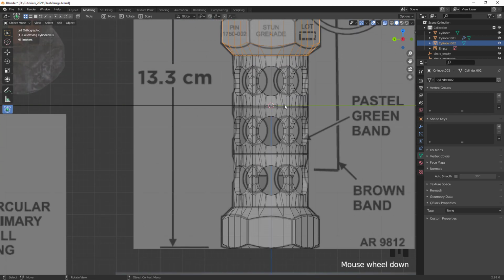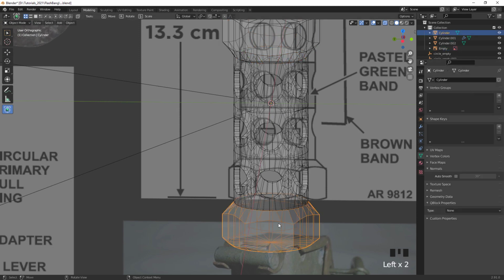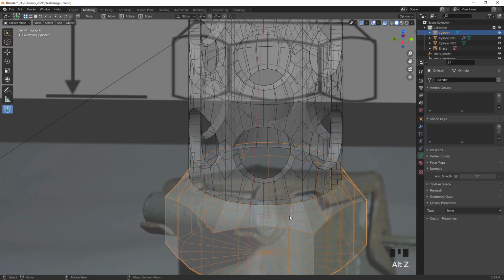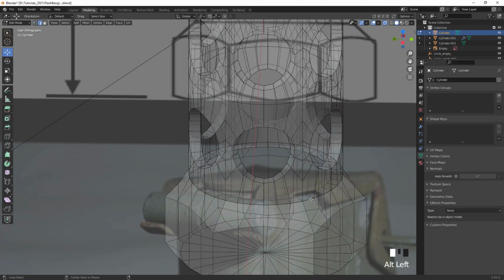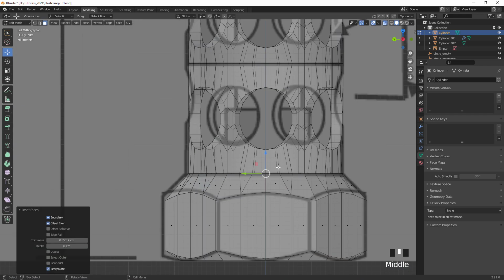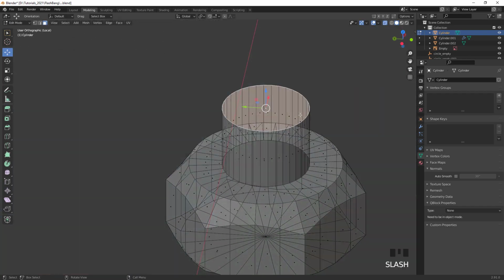So now we have made use of the same element from the bottom at the top, and we didn't have to do the work twice. So we are gonna treat these objects differently though. I'm gonna take this element here and say F on it while we have an edge loop for it. And then I'm gonna use the inset to essentially have an extra loop there. And then that selected loop we can bring up with an extrude.